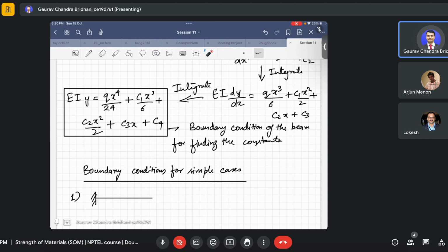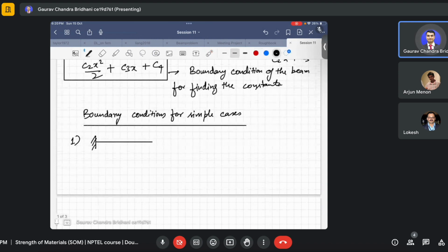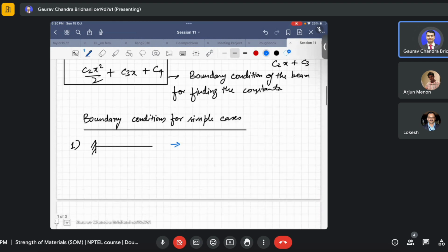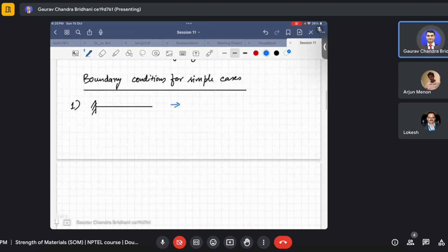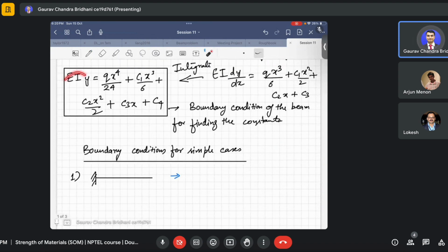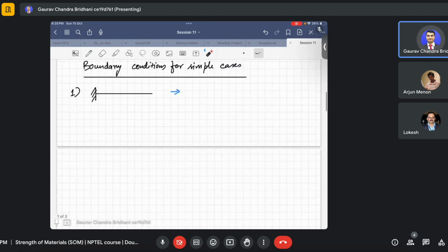We have to write in terms of bending moment. If we have a point load or something different from the uniformly distributed load, then this final equation of y will come up in a different form. However, the boundary conditions won't change. They depend on the geometry of the structure or the kind of supports we use. So it doesn't depend on the loading, only the moment changes basically.